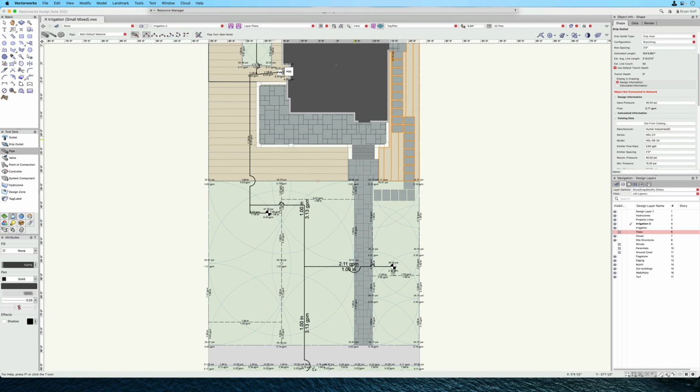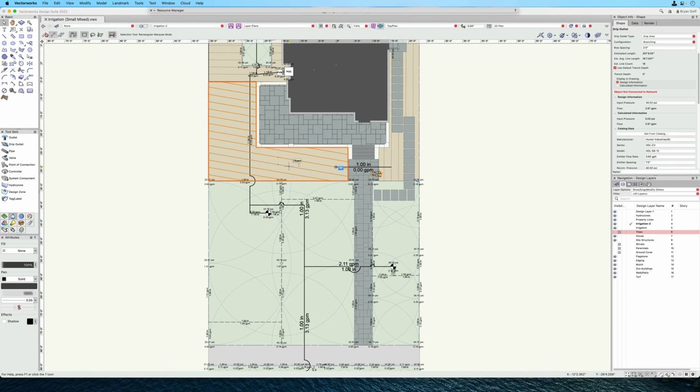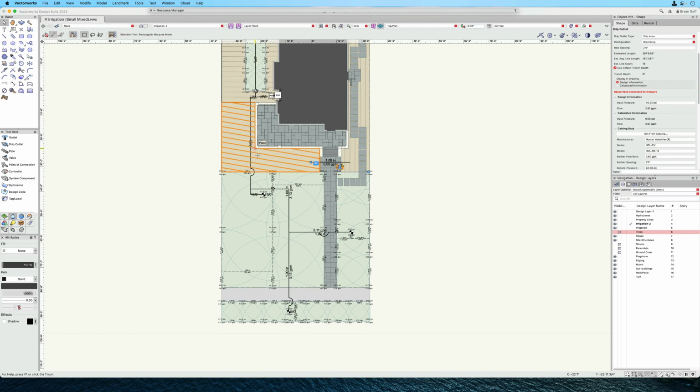I'm going to use the pipe tool. And you'll notice that I can either find the end point or that connection point, or I can just click anywhere here. And I'm going to pretend like I have a sleeve that runs straight across, and away you go. Now notice what happens is it does redirect where that connection point is, which means that your anchor point is going to be different, or your direction point. So I can define that direction point if needed. In this case, I'll run it horizontally that direction, and I'm good.